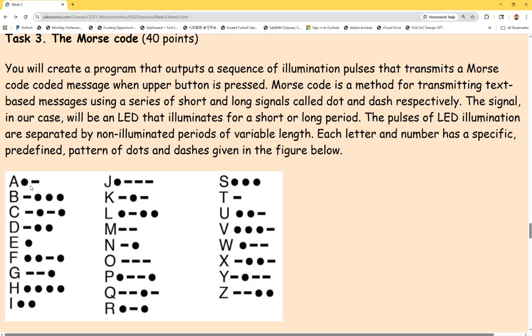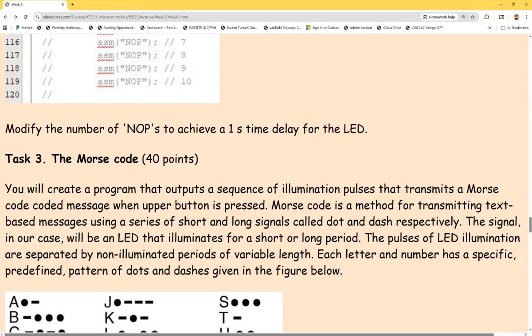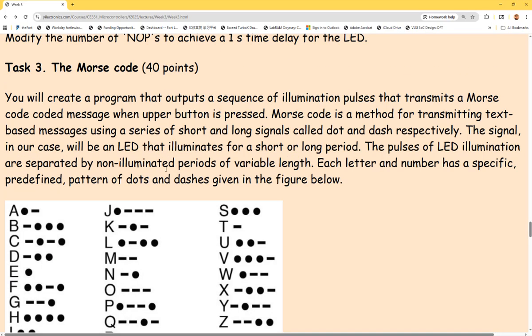It's actually really simple. You do a digital write, and you delay it with a certain amount of delay. If it's a dot, you do this amount. If it's a break, you do this amount. That's it. But the delay has to be right. So for this one, you turn it on for a certain amount of delay for the dot, turn it off for the break, and turn it back on again for a certain amount of delay for the dash. That's the letter. And there will be an inter-letter delay as well, since if I'm doing SOS help, there will be delays in between the letters. So that one has a different time delay as well.